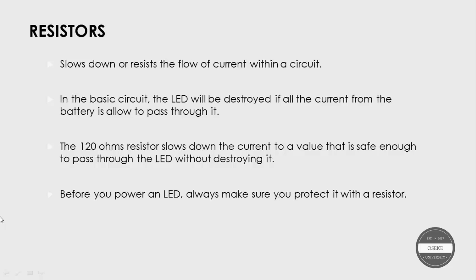Before you power on an LED, always make sure you protect it with a resistor. If you power on an LED without a resistor in series with it, you risk burning out that LED, and that will probably be one of the first mistakes you make when you're building circuits. People short circuit LEDs. Even when you're testing the LED, you should put a resistor in series with it to avoid burnout.